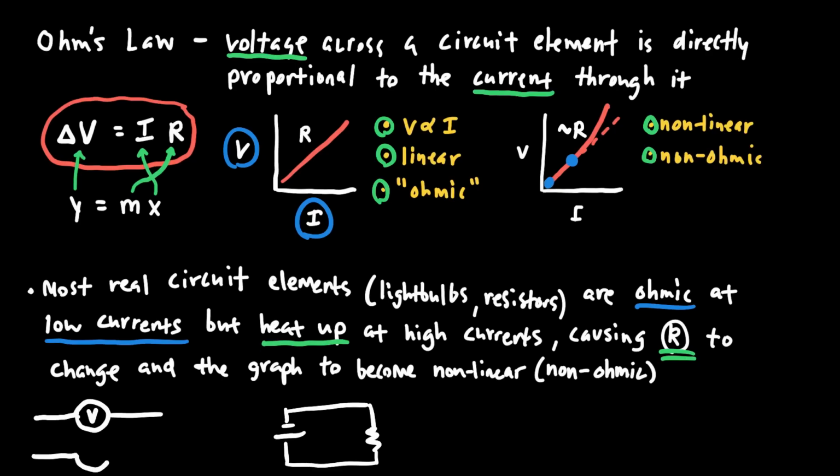And then the symbol that I use for an ammeter, which measures current, is a circle with the letter A in it. And so in my circuit, how could I represent that I'm including those meters in the circuit in order to make some measurements? The way that I could measure the voltage across this resistor is I hook up the voltmeter in parallel with the resistor.